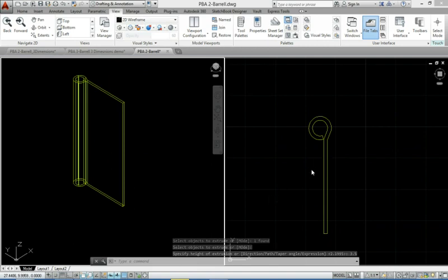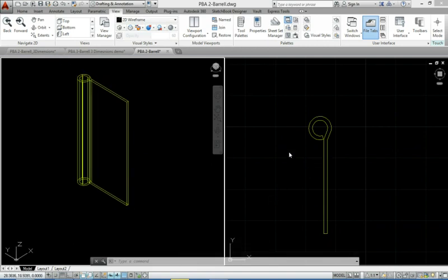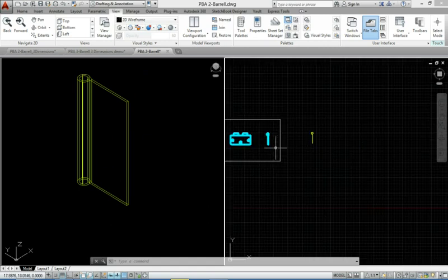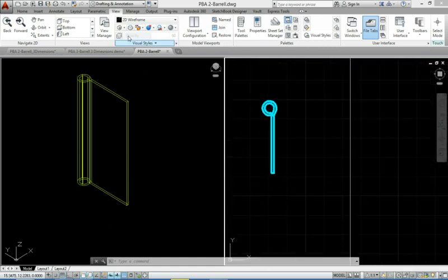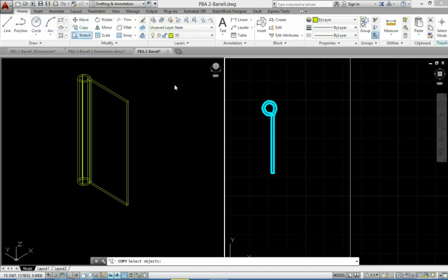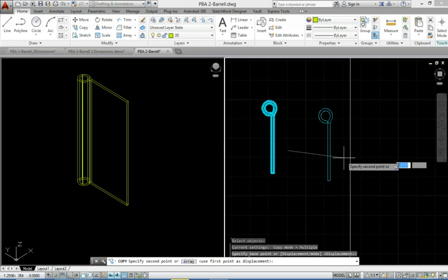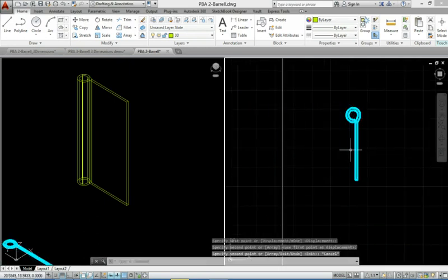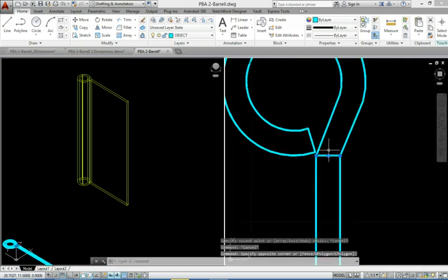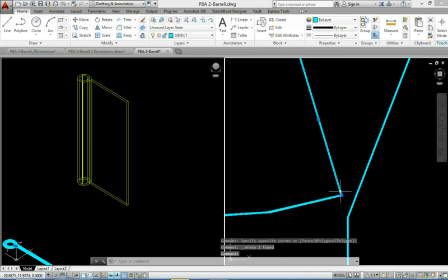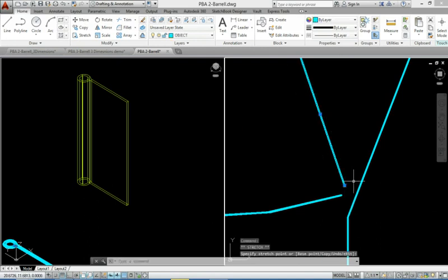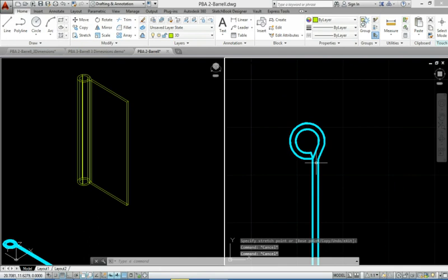I'm going to show you an incorrect extrusion so you know what to look for if you did it wrong. Let me copy this over again to demonstrate to you an incorrect extrusion. I'm going to purposely break this open somewhere so it's not closed, even though it looks like it's closed from a distance.